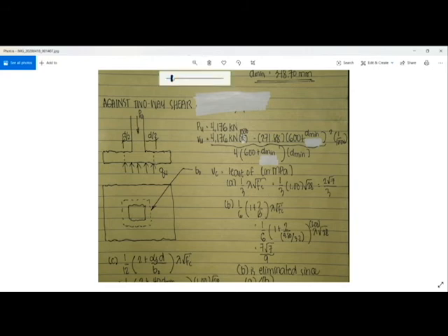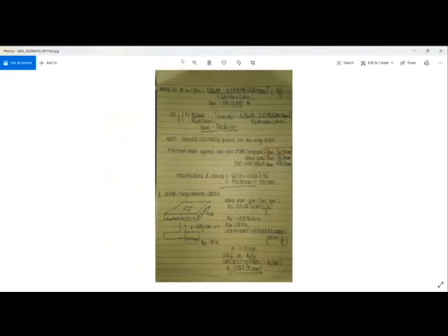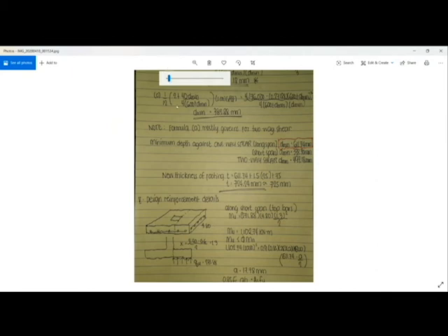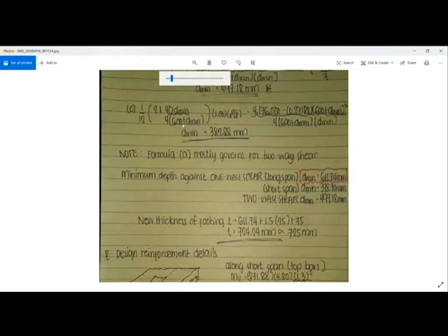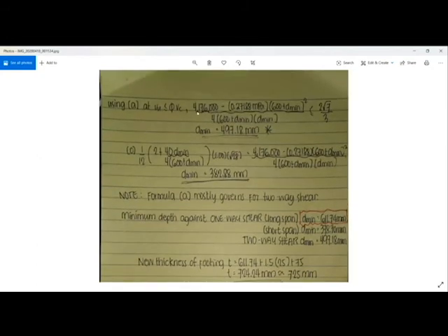Okay, so let's proceed. If we use formula A as our Vc, we use 4176 minus 0.27188 times (600 plus d minimum) squared, over 4 times (600 plus d minimum), multiplied by d minimum, is less than or equal to 2 square root of 7 over 3. Our solved value for d minimum is equal to 497.18 millimeter. That is if we use formula A.